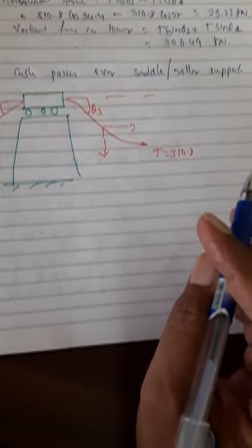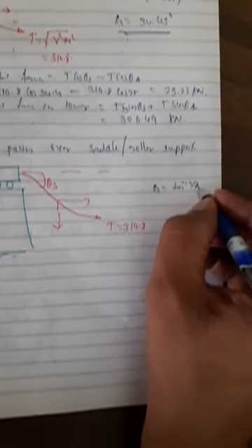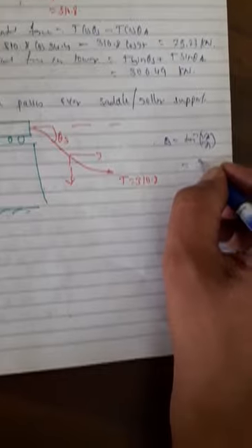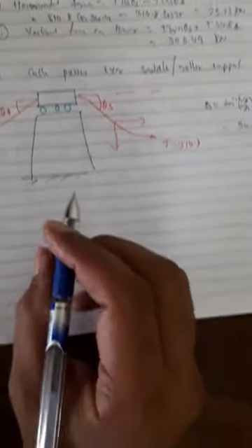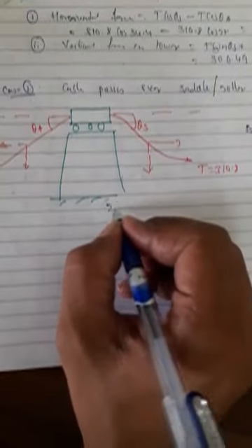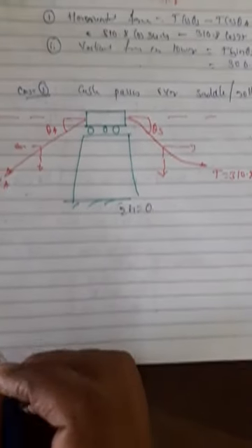Again, theta S is equal to tan inverse VA by H, I know the equation already. I get theta S as 34.3 degrees. Now for the stability of this equilibrium, I can write summation H is equal to 0.